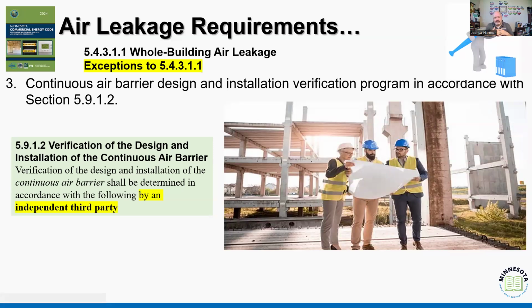That third option, right? So we have whole building testing, and then under that, if it was over 50,000 square feet, we could do the compartmentalized partials. We could do it if it came close. We could do smoke tracer or thermal imaging verification of deficiencies.